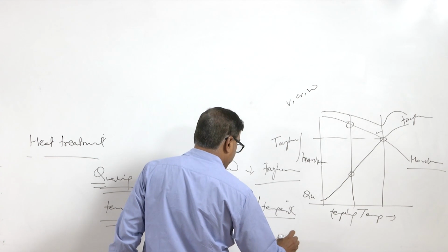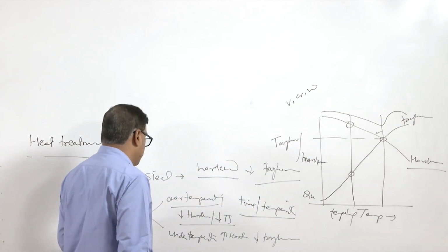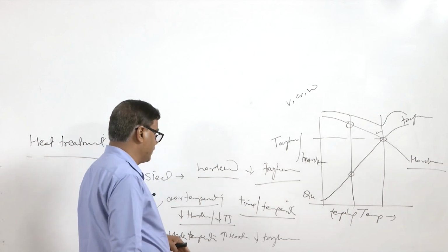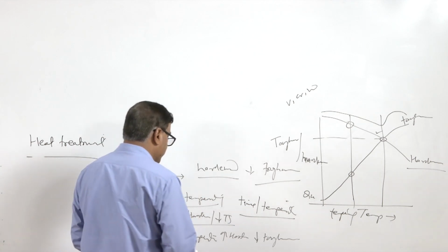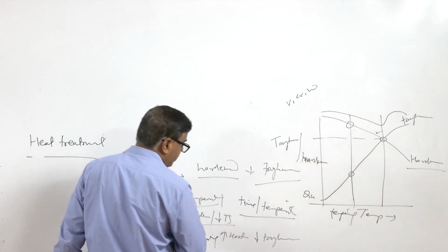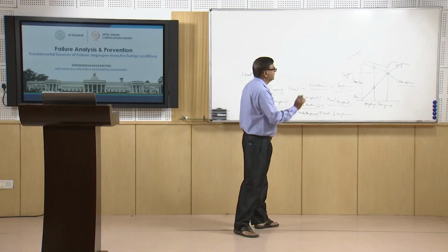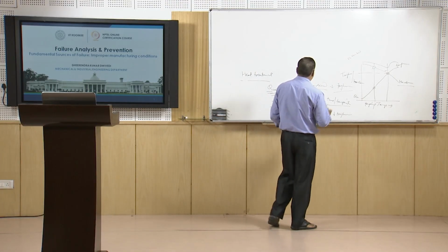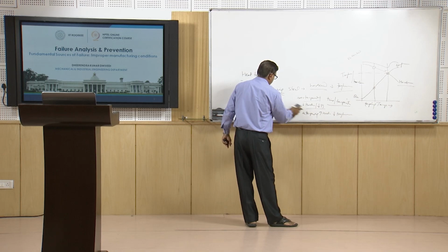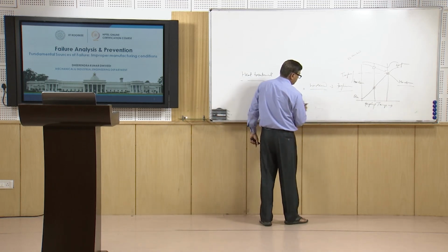So, for any given application, it is required that both over and under tempering are avoided, so that we can have the optimum tempering wherein we have the required combination of strength and hardness for achieving the required mechanical properties in the steel after hardening.